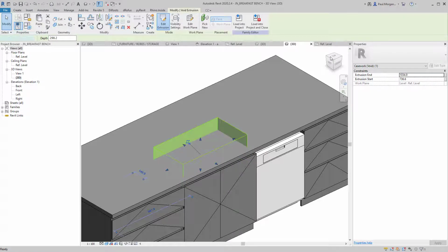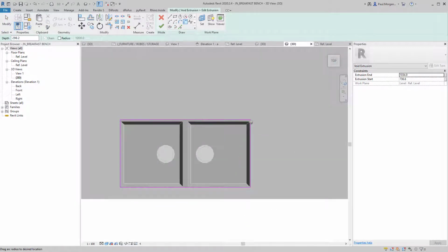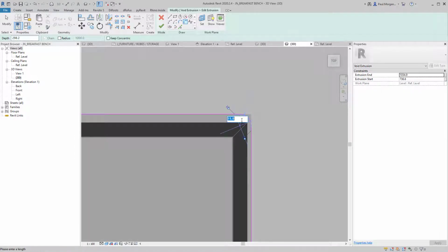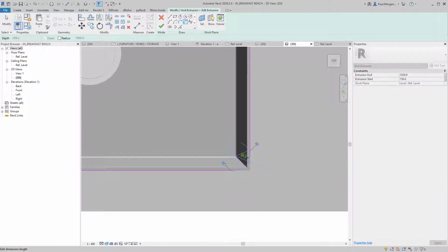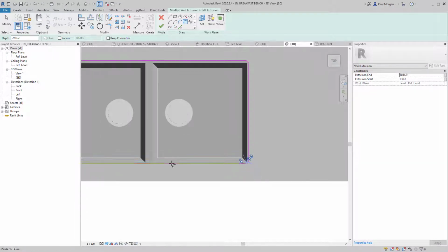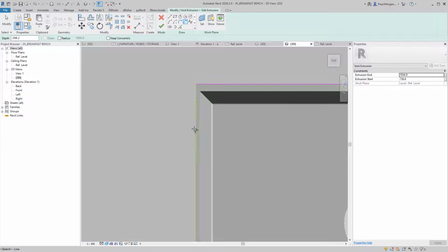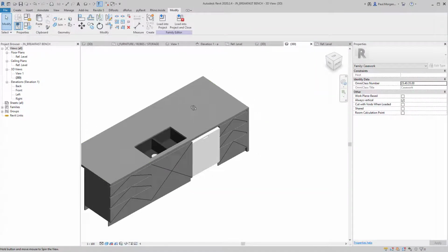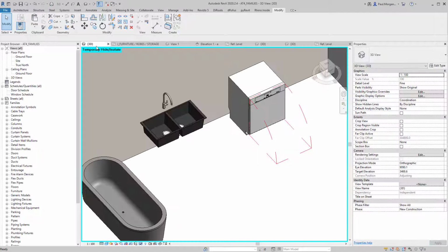Actually, that void extrusion, I'm getting a little bit finicky now, but I'm just going to fillet these edges ever so slightly, just because they won't cut a stone at a perfect right angle. And I'm just adding a 10mm radius to each of the corners of the void extrusion. That's better. Okay, so now let's go back to our family model.